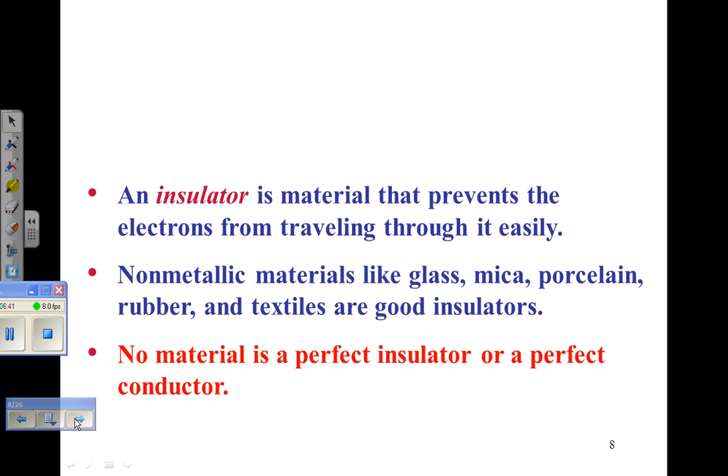Because, for those who don't know, electrician's tape is only intended to keep moisture out of the connection. It has nothing to do with insulating properties because it's not a very good insulator. Can you name a better insulator than vinyl tape? Porcelain. Porcelain's a vastly better one. How about paper? Plain old paper is a vastly better insulator than rubber, even. There are places where they use purified mineral oil and paper to insulate high voltage cables.